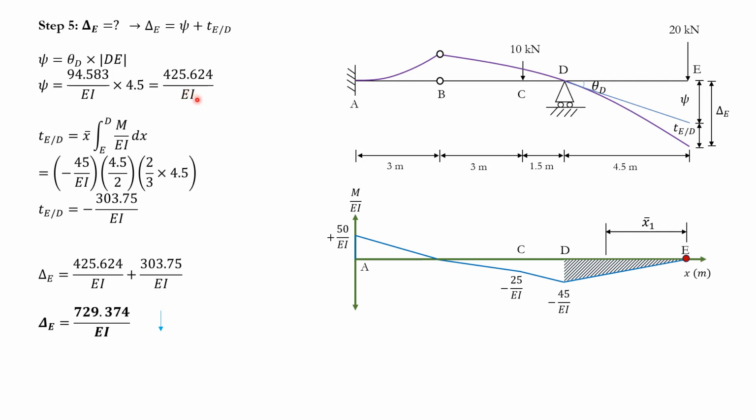The only place that you really use the signs very consistently is the rotations when you're using the first theorem. That's all. Otherwise, you always have to look at the elastic curve itself and see what you're dealing with, okay? And so, yeah, that's it. So that's how you find your deflection at point E. And of course, I can see from the diagram that it's going down, right? So this is the initial point, it's going down, right? So that's why I just put a sign here going down, and that's it.